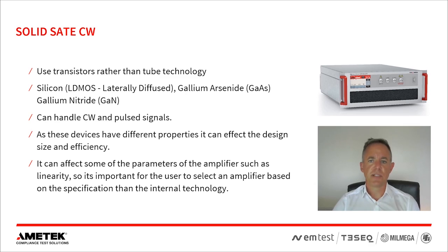Solid-state amplifiers can produce a specified rated power either continuously or pulsed, and are available in many frequency, power, fit and form combinations. The relationship between frequency and power is that more power is available at the lower end of the spectrum and then gradually declines as the frequency is increased. For pulsed operation, a CW amplifier can have a duty cycle up to 100%, though it's important to note the output power will diminish at these high duties. Higher power can be achieved at lower duty cycles as the efficiency of the amplifier improves.